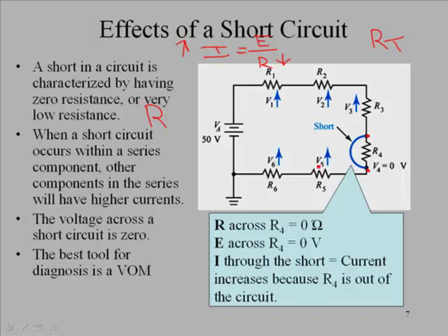And you see these little blue arrows here, and they have a little V tied to them. This is indicating that the voltage across all of these components will suddenly be a little bit higher. Now the reason that the voltage is a little bit higher is because of this. One of the resistors has been removed, shorted across, so resistance has gone down, current has gone up, and so all the voltages have increased a little bit.